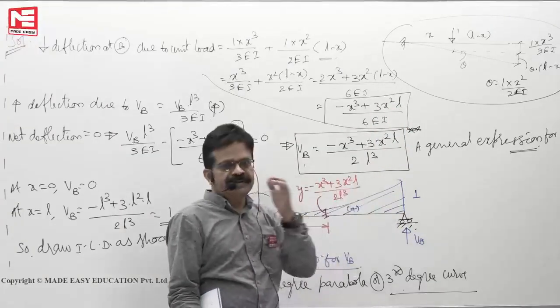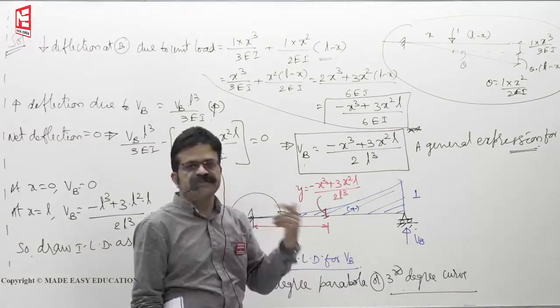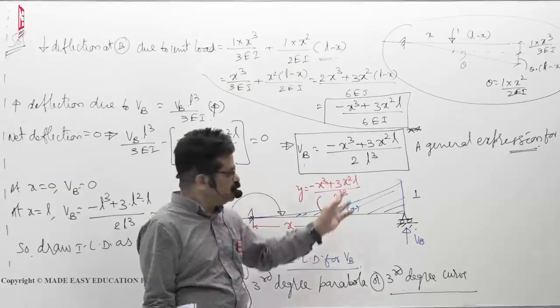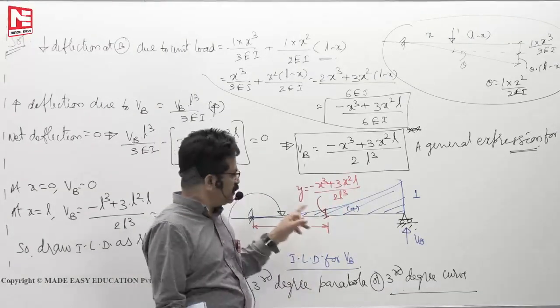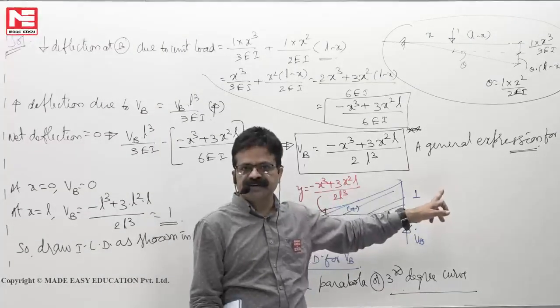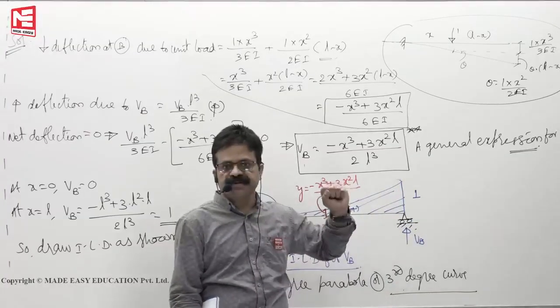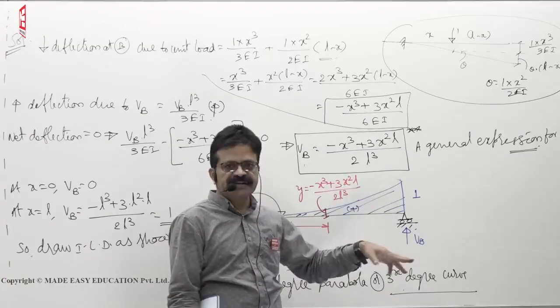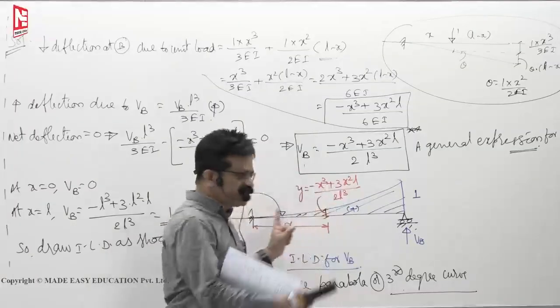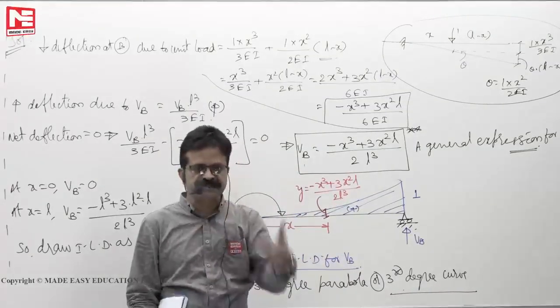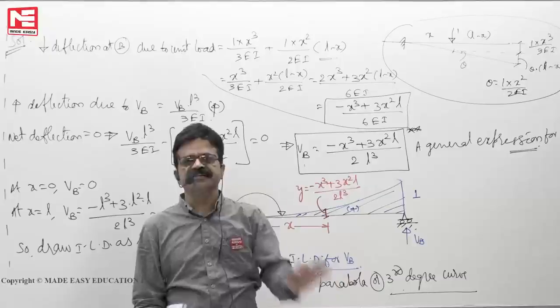So that cantilever deflected shape is the influence line diagram. So you get a third degree curve. That's the reason why you got a third degree curve here, because it didn't become unstable. Removing the reaction will not make it unstable. But for a simply supported beam, if you remove the supports, it will fall down. Now if you lift it as a rigid body, it will go up.